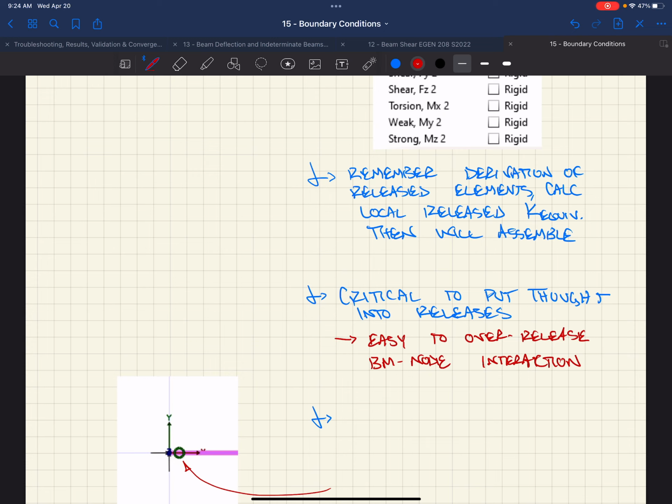Say we had a building that was 2 stories, and you decided to run a beam across the entire second floor, and it was continuous, and you decided that you just wanted to bolt the top flange of this column to the bottom of this beam. I would say that the stiffness of this is pretty limited, right? So you might want to release this, something like that.